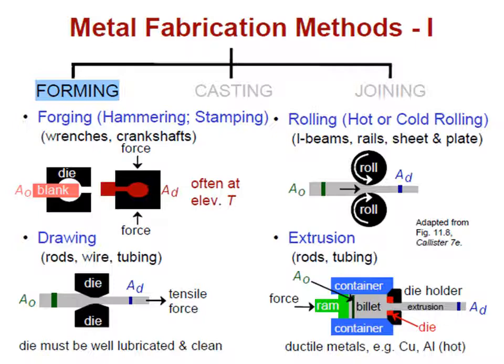Another one is drawing. This is also a type of rolling, but it is different. You can get rods, wires and cables. The die must be well lubricated and clean. With the tensile force you will be getting it.